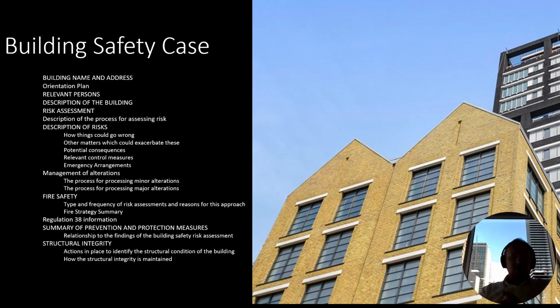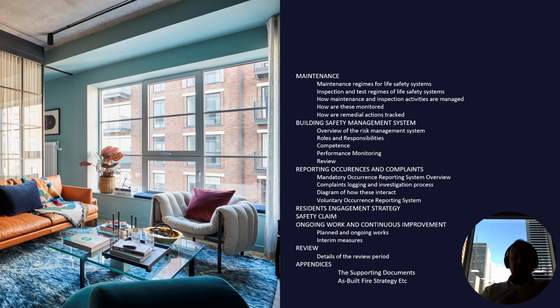And then all of that information can then be utilized to form the building safety case. So all of this information that's required in the safety case, all of that will be in the golden thread. And the building safety case report should be relatively straightforward to compile then in that case, because all we're doing is pulling information from the golden thread and assessing it against the information itself, and cross-checking it, as well as cross-checking that with the building itself as well.